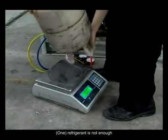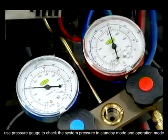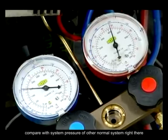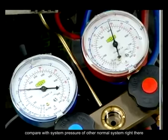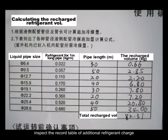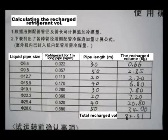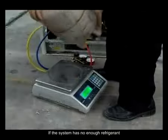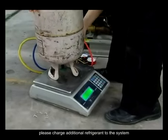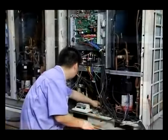1. Refrigerant is not enough. Use a pressure gauge to check the system pressure in standby mode and operation mode. Compare with the system pressure of other normal systems nearby. Inspect the record table of additional refrigerant charge. Then judge if the additional refrigerant is too little or the system has leakage. If the system does not have enough refrigerant, please charge additional refrigerant to the system and find out the root cause of why the refrigerant is not enough.